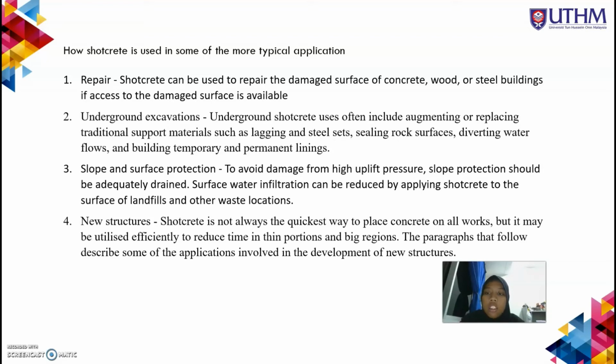Next, underground excavation. Underground shotcrete uses often include augmenting or replacing traditional support materials such as lagging and steel sets, sealing rock surface, diverting water flows, and building temporary and permanent linings.